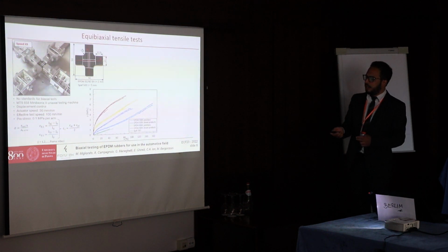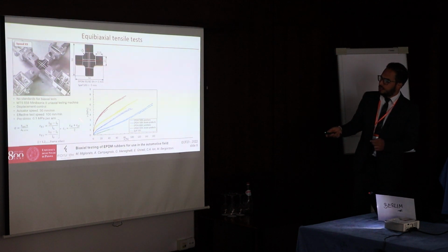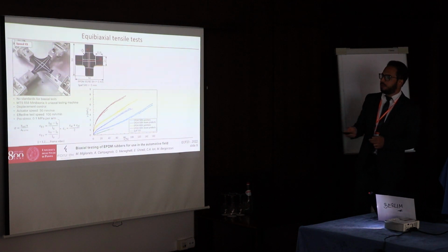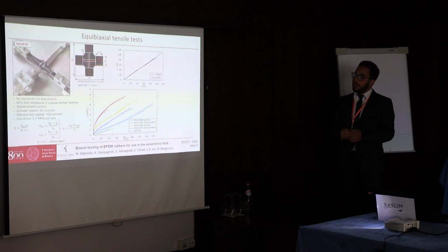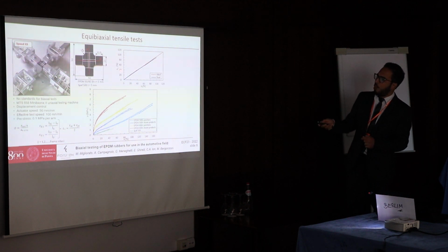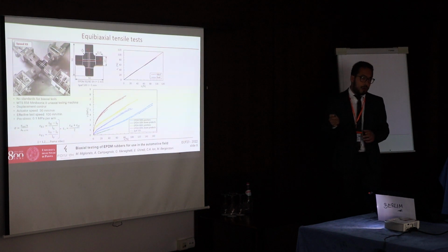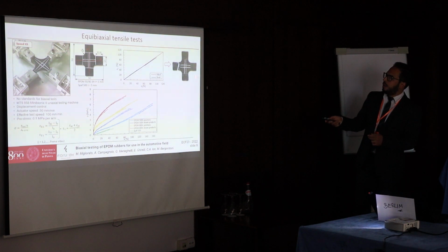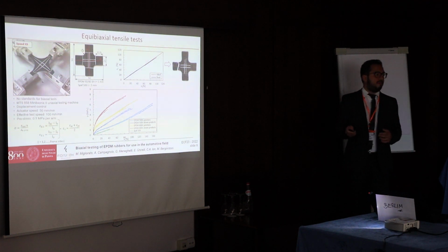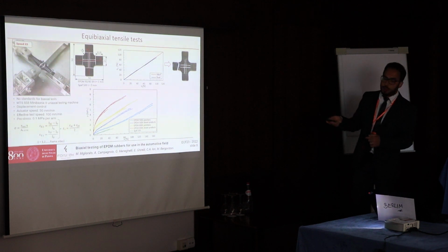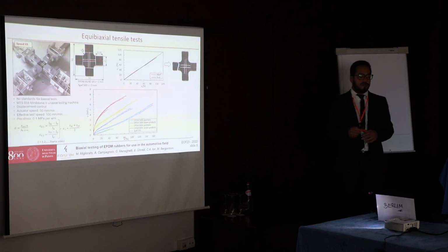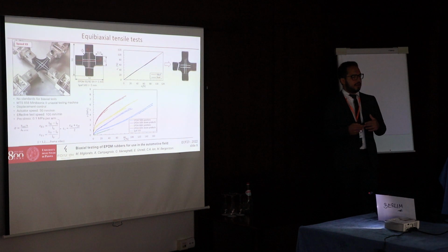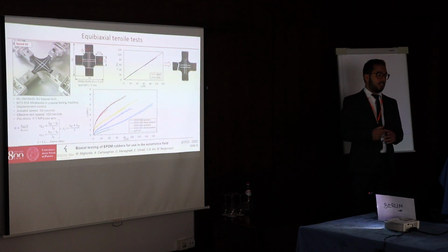In this way, we have obtained engineering stress-strain curves of all tested EPDM materials, and it is worth noting that the strains measured by the DIC system along the y and x direction were equibiaxial. However, all specimens failed on one of the arms and not in the center of the specimen where an equibiaxial stress state exists. Therefore, the failure stress and strain cannot be considered as characteristics of a material under equibiaxial loading.